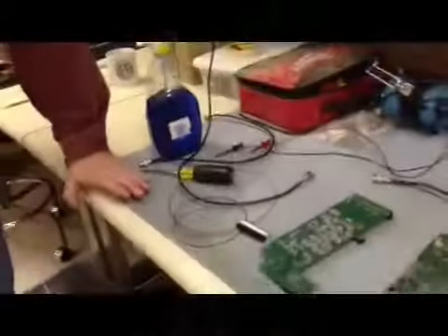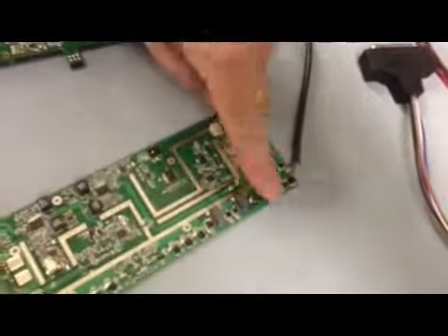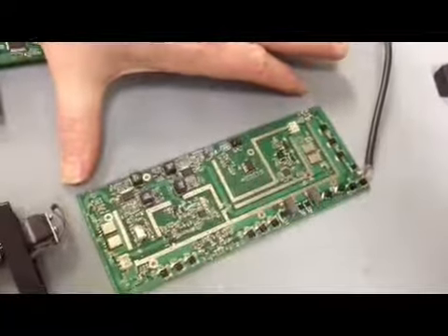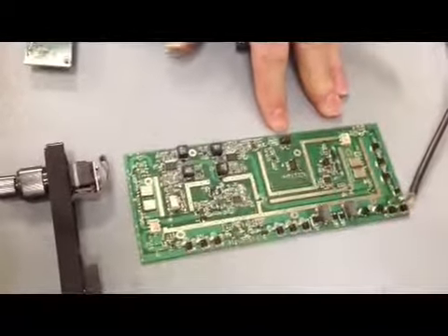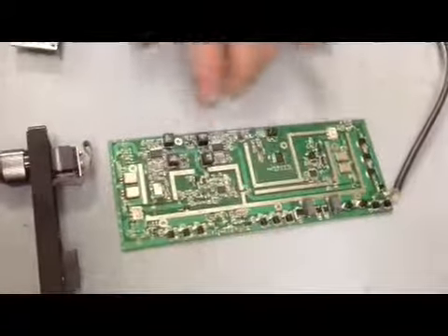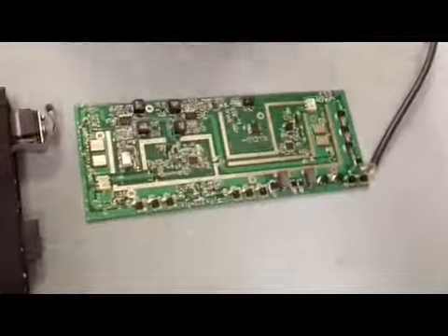Today our goal in testing is to test the RF divider, which is this small filter section here, as well as the overall operation of the NAV board. We have some limited code installed in the microcontroller so that we can start up at a set frequency and have the two demodulators do their job, as well as the mixers, which give us our IF frequencies and allow us to hopefully receive signals today.